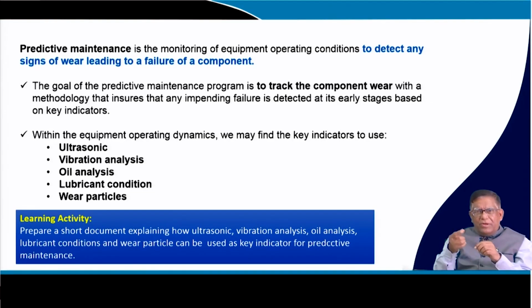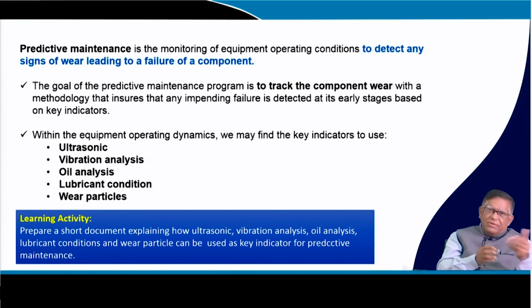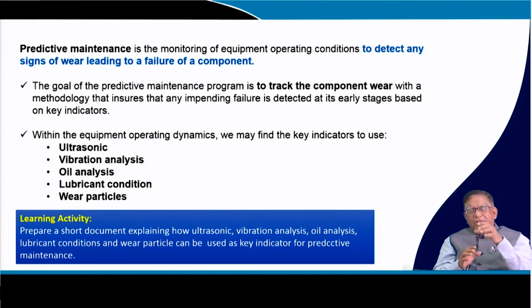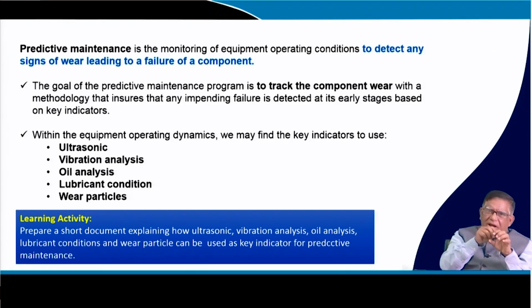If a doctor asks you to give a blood test, you go to a maintenance engineer and say: is there oil contamination, has your oil got polluted? They will start this oil analysis. From the oil they will find out. You might have heard, in engine oil, if a lot of debris is coming, it means something inside your car engine, where the fuel is getting burnt, is wearing.